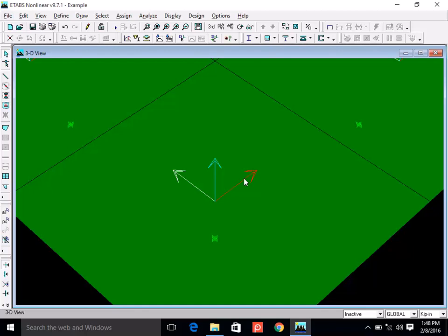But if it is 4-sided supported, for example, this panel, look at this panel, it is 4-sided supported, but if you get the B over L ratio, then that will tell you that this panel is one way, which means that it should bend like this. Okay, that's your span. But it doesn't mean that it will not bend in that direction. It will, part of it. Okay. In theoretical manual calculation, we ignore that. But when you do finite element analysis, you will have some bending moment in the other direction as well.